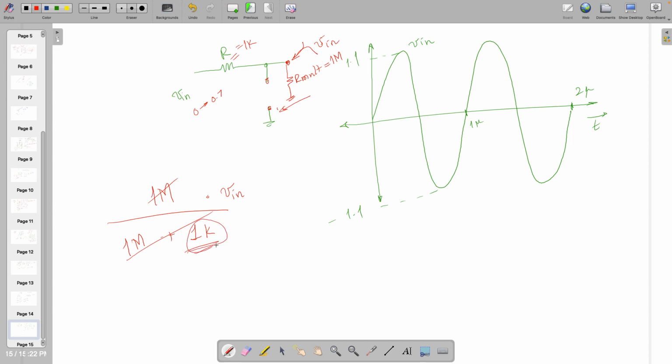That error is coming because a very small number will be coming, right? We are not going into detail of that, but if this is the case, when it becomes open circuit, do not forget that there is one more circuit, which is the multimeter, whose impedance is 1 mega, offered by this multimeter. So whenever you are saying this is open, its V in is transferred over here, right? So this is the case. So let's start. If it is 0.1, it's transferred, no problem till that point. If I give 0.2, same thing is happening, this is becoming open circuit.